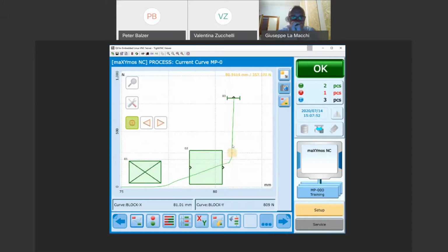Please do not drive more than 10 millimeters per second against a hard block. You will exceed the target value big time, and also it's not worth it, because the joining system can be damaged. And of course, you won't really decrease your cycle time. If you use a setup like this, it's much better, and regarding the cycle time, it's also quite faster.